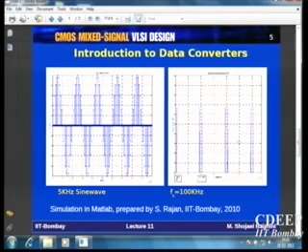Suppose you have a sine wave, starting with a simple 5 kilohertz sine wave. You sample it with a frequency of 100 kilohertz, and you can do this simulation easily in MATLAB. Some of you may have done it before. It's a simple example: these are now samples of the signal, and then we go to the frequency domain. You can plot it in the frequency domain.